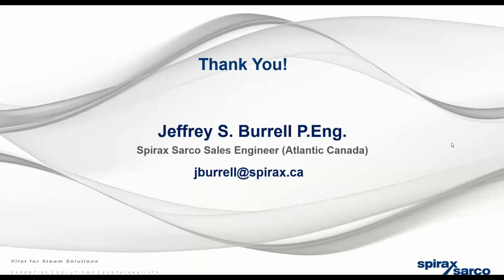So Jeff, what do you think about rectifying in already existing systems? If someone already has piping done, do you have any other ideas? It just brings to mind a lot of questions that come to mind at site. But if I have a single steam trap, do I need to capture that flash steam is my first thought, or can I subcool it and take it to drain, basically take it to grade?